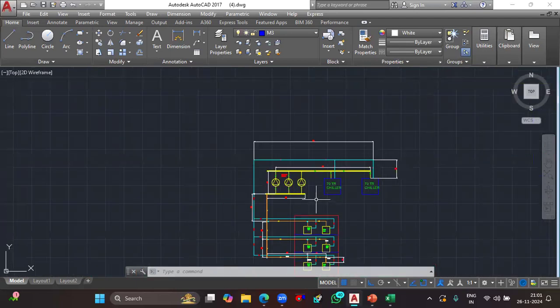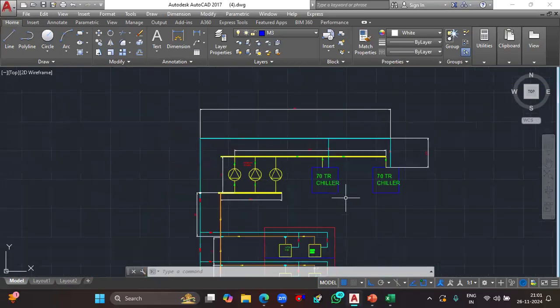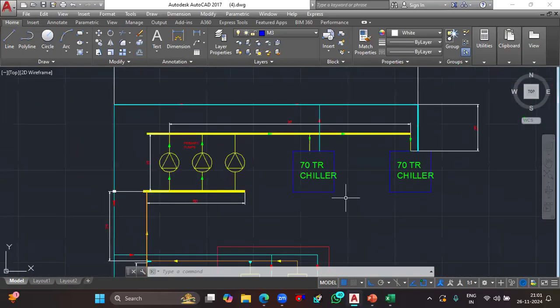That is the concept of this. Okay, clear? Actually, it's not the exact concept, guys. Why? Because here I just randomly said it has to be 140, but in real life projects, the flow rates are different. That should be easily calculated according to the chiller itself. For each pump there will be an allocated flow rate. It should already be mentioned, like 200 lph, 500 lph, and we can convert that into GPM. It's your spec. That's it.